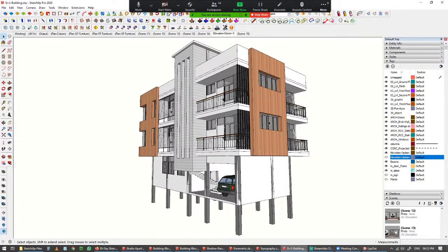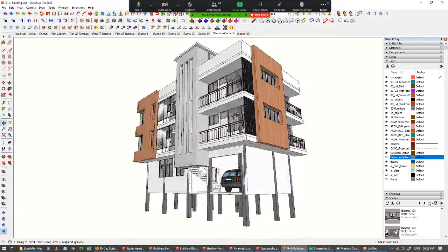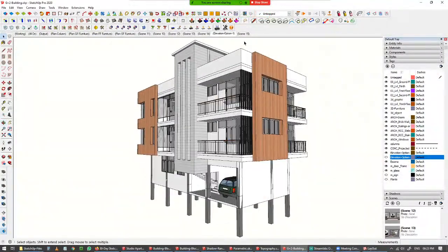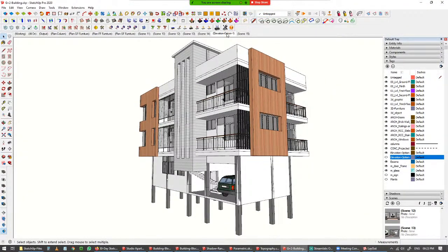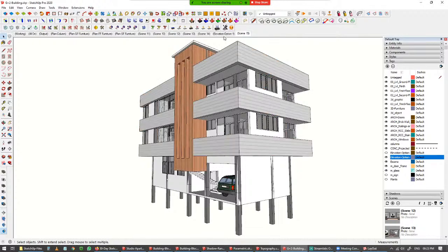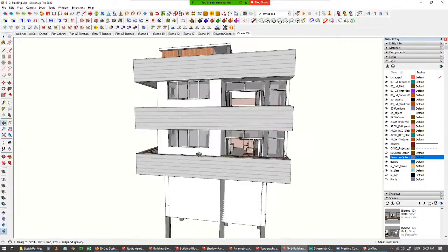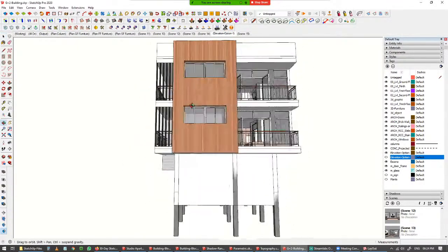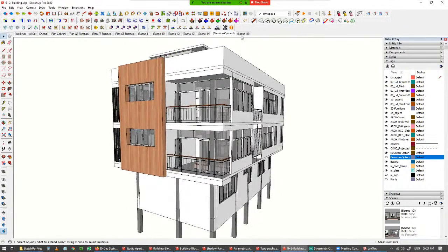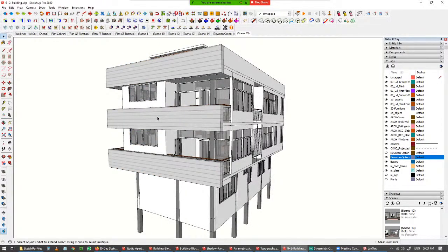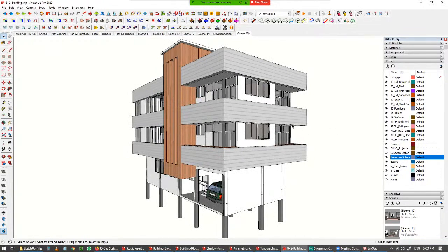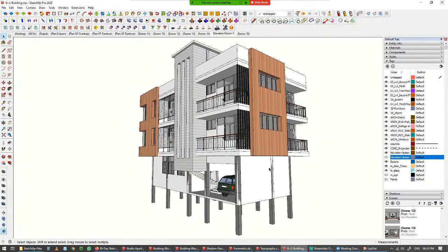That means this is an elevation design proposal. Now this has got elevation option 1, and we have another option for the elevation, which is elevation option 2. Now I can quickly switch between those two, and you can see that without creating two different models, I can have two separate options. I can even rotate and I can switch to another option.